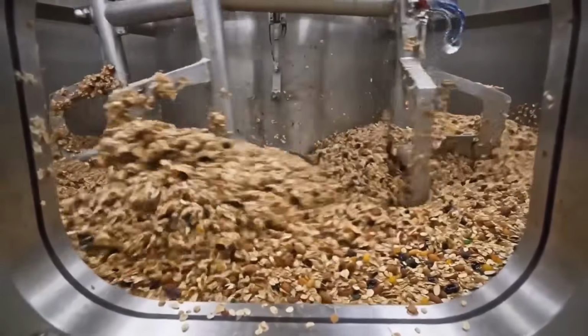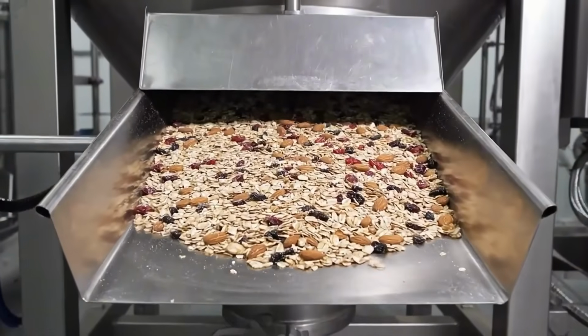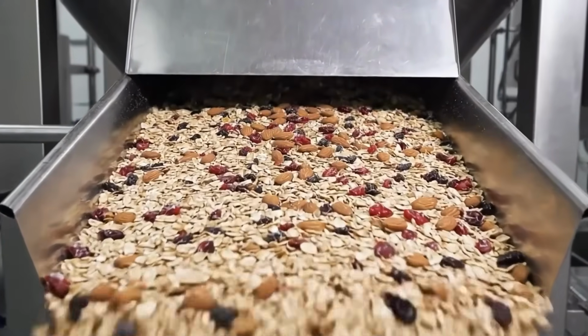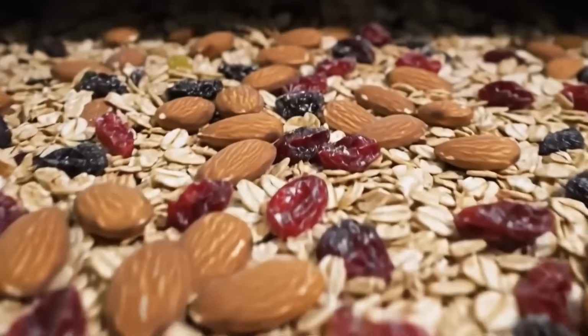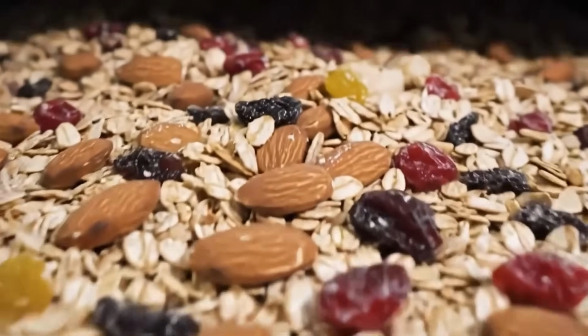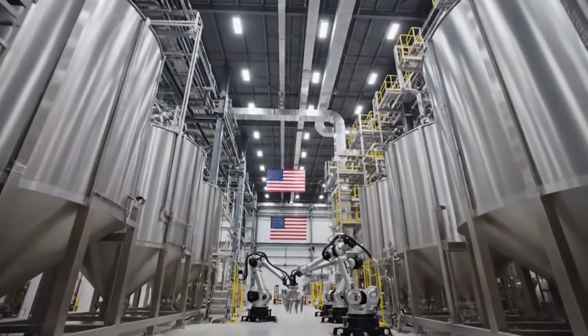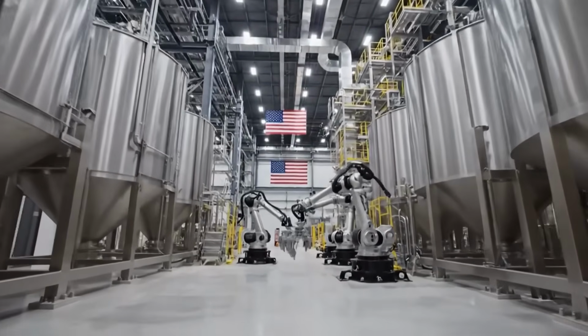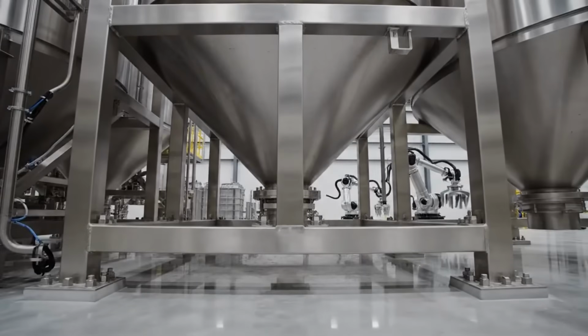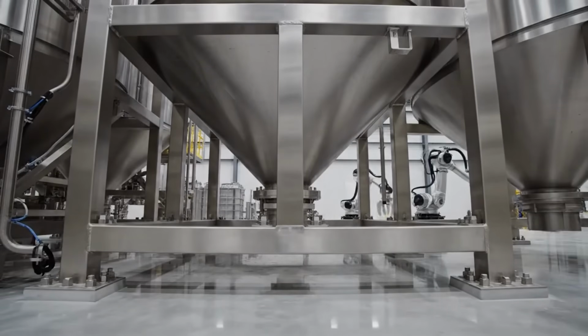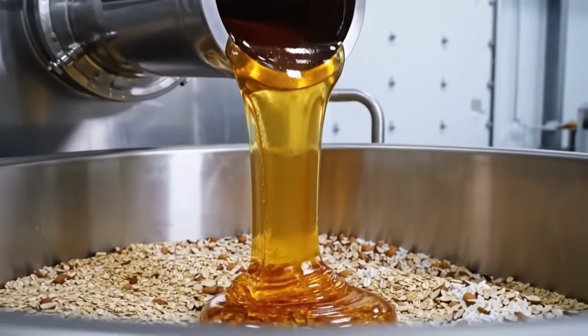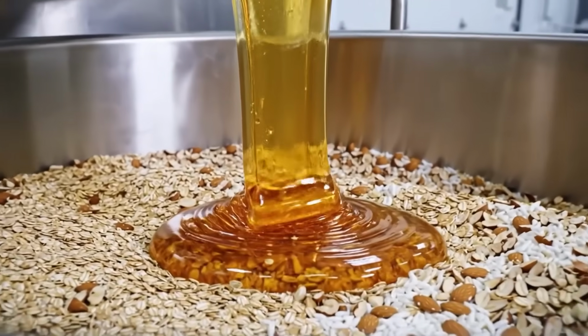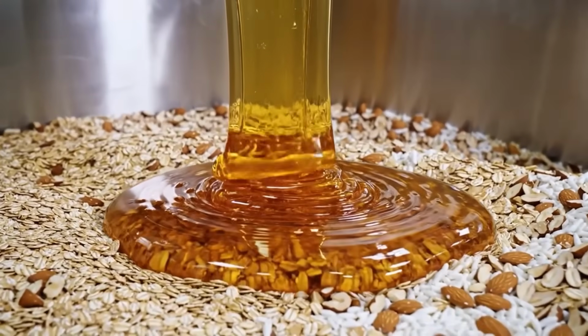Vanilla and spice extracts are injected, so aromatics are preserved. If fruit concentrates are used, they are blended in at controlled temperature, because they can burn or separate when overheated. Acidulants can be added to balance sweetness and also to manage microbial stability. The binder is mixed until it is uniform, and then it is pumped to the forming line.